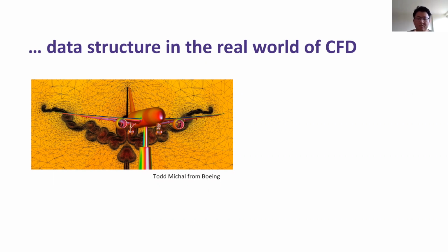When I recall your aerodynamics class, one of the most important characteristics in modern aircraft is the wingtip vortex. The wingtip vortex is basically caused by the pressure difference between the upper and lower wings, which makes the air from the bottom move to the top, and the byproduct is a pair of vortices. The pair of vortices requires a smaller mesh size to accurately resolve.